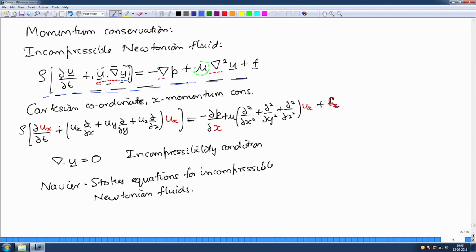I should once again caution, this is valid only for incompressible fluids. Density is a constant, viscosity is a constant. Only then are these equations valid. Where they are valid, they have a form that is remarkably similar to the concentration and temperature equations. A Laplacian of the velocity on the right side and the velocity derivative plus u dot grad u on the left side.